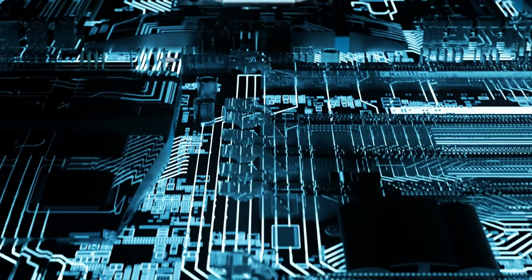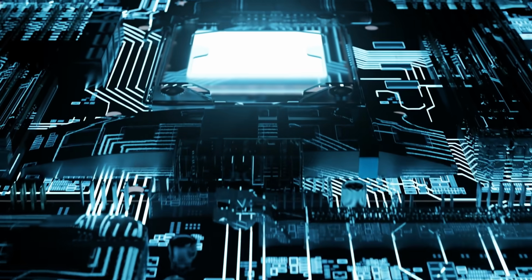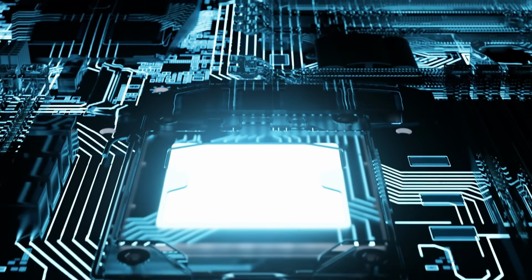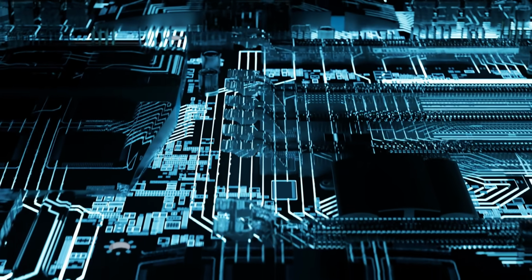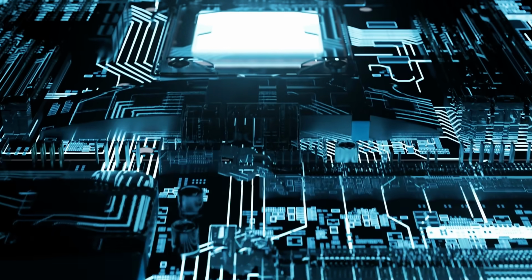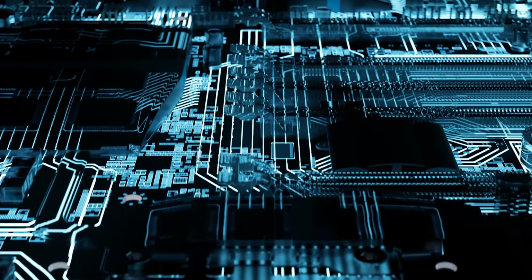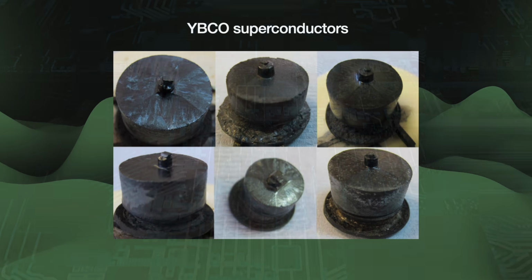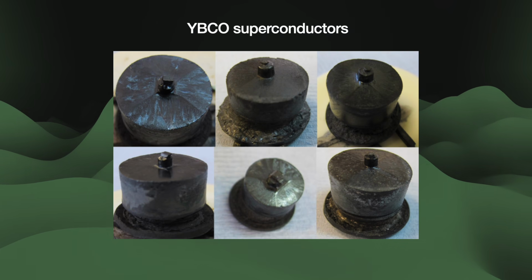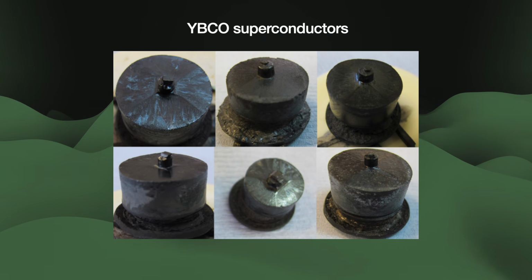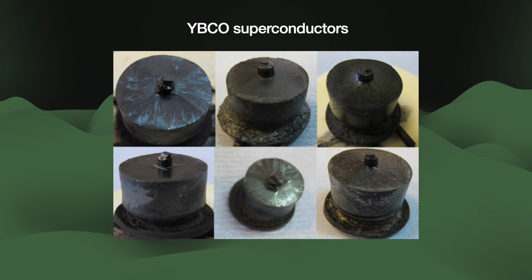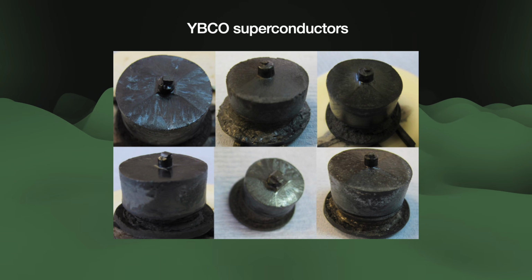So in order to run integrated circuit operations and stay under those limits, the interconnects have to be very wide, perhaps even a centimeter wide, which for most digital circuits is unfeasible. This is why the cuprates never made headway into the integrated circuit arena. LK-99 or any room temperature superconductor may suffer the same issues. If so, then it is just a scientific curiosity, and copper retains its dominance.